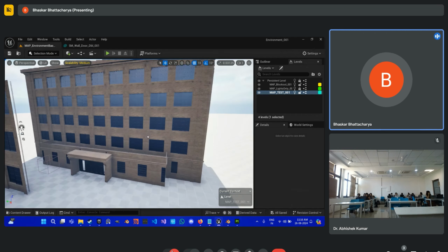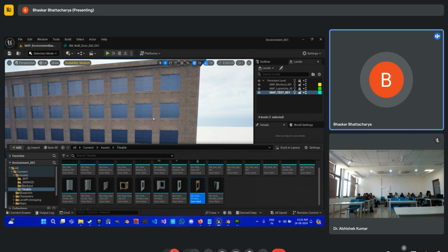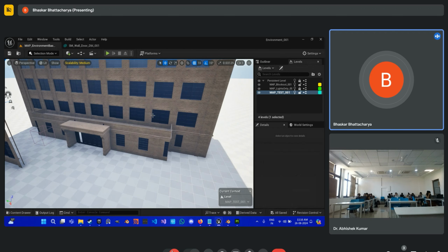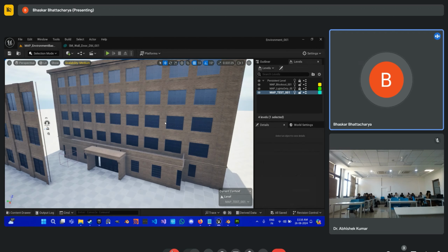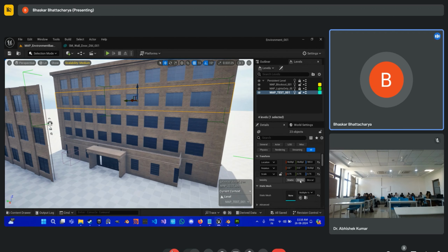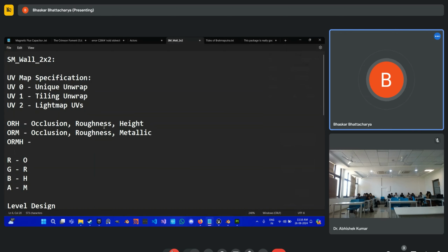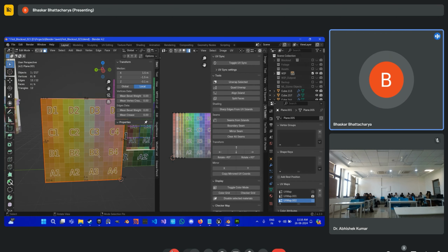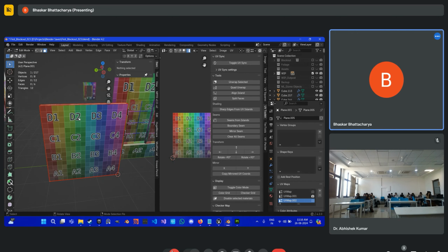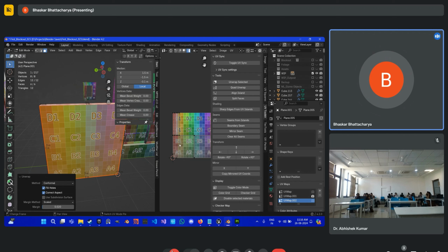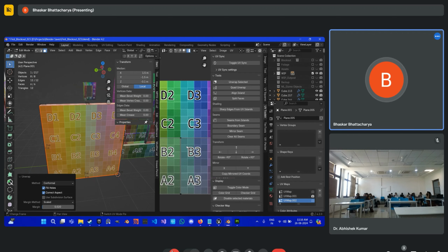For that, Unreal has static lights and stationary lights, which bake light information into any mesh that is marked as static. We are going to come to that eventually. For now, all you need to know is what baked or static lighting is. In order to store that information, we have the light map UVs. Now, light map UVs are again very unique. So for that, what I'm going to do is first of all do a regular pack.